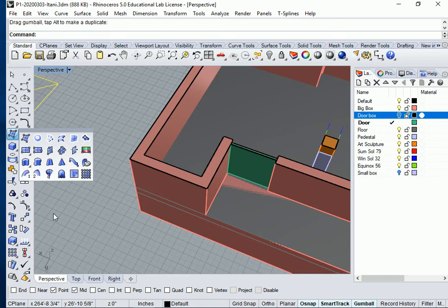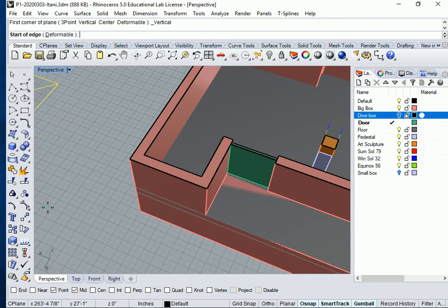So you can just do a vertical surface for the door, right? You enter your dimensions. You can call this 3 foot 6 inches away. You accept it, then you take it tall and you tell it I want it to be 7 foot tall. There you go. All right.